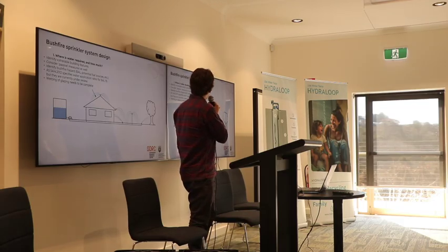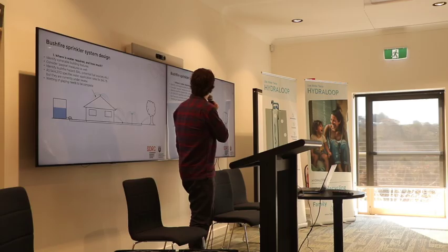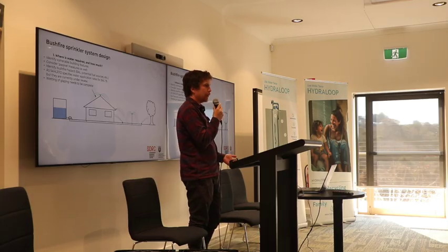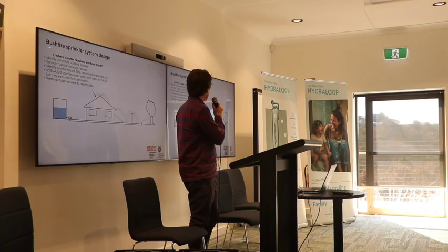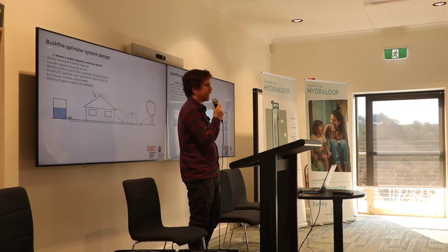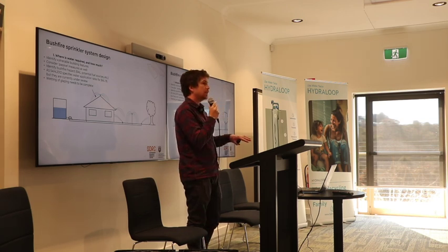The standard AS 5414 does give water application rates, which are required for BAL 19. That's the level of hazard that you'd be facing. But there's not much quantified guidance on how to adapt that to other hazard levels, which we're hoping will be improved in the standard when it gets updated. Another important point is that if you are spraying windows, it's very important to wet the whole surface of the window so that you don't introduce thermal shocks which can break the glass if part of the window is cooled and the other parts aren't.